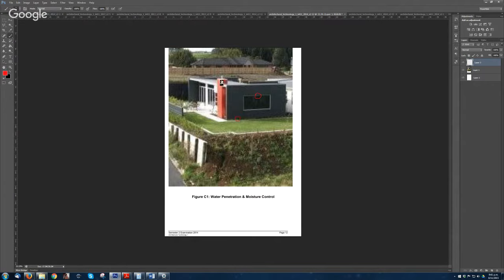Another one would be the chimney. For the chimney, you have it on the side, like if the flashing is not done properly, the metal part that's covering the roof, the water can get inside. You get some roof penetration here. So the water can get in, and with most roof penetration, the process is by gravity. If there's a hole, the water will just go in there and drop down.